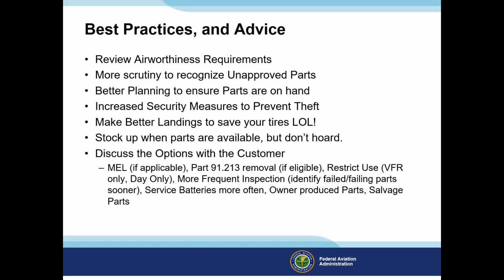And as mechanics, you can discuss the options with the customer. If they have an MEL, use the MEL. If not, and the criteria are met, you can use 91-213 for removal and placarding or deactivation. Restricting use, VFR only, for example, or day only, if it meets the requirement.